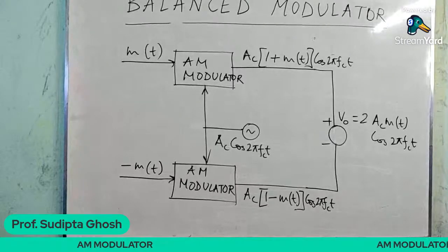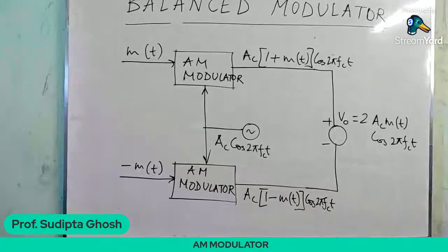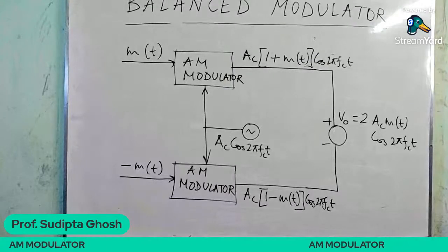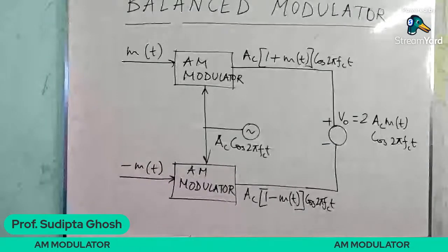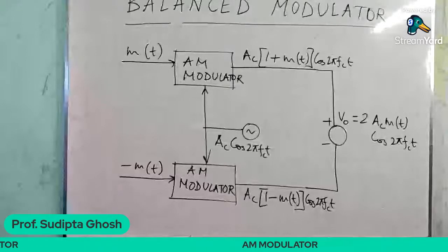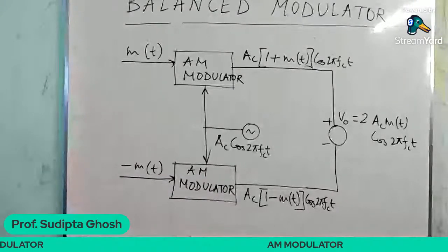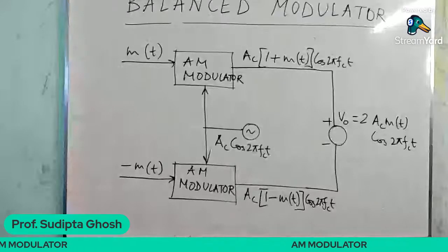Now I will discuss how this circuit works. The concept is to suppress the carrier component, so let's discuss how mathematically the carrier gets suppressed.